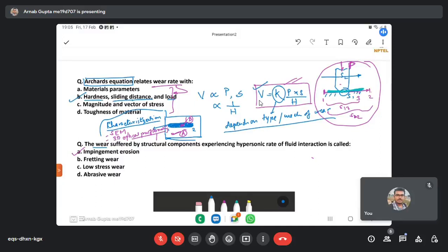Okay, as you're saying, it is the loss of material, but it can be the loss of shape also, right? So from the surface, suppose this is your initial surface, you haven't lost any material, but your shape changed like this. That is also a type of wear. So you have heard of brinelling, right? So brinelling is also similar to this.